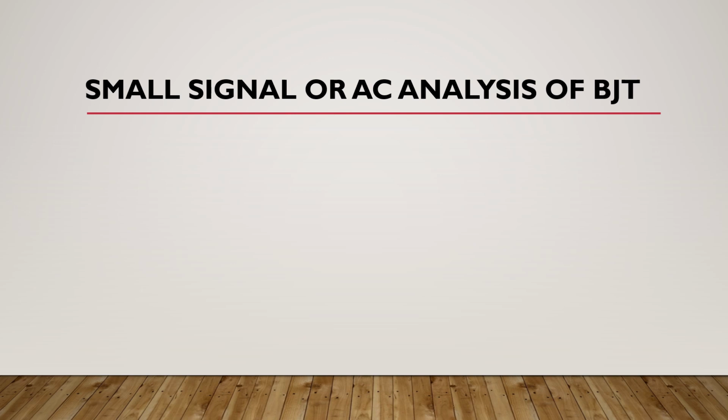Now, if you have a transistor configuration like this, and the arrow is here, it means this is an NPN transistor configuration where we have RC here, here we have VCC supply voltage, and as you can see this source is connecting base and emitter, and it is a DC source as well, so we can write it like this, because we know that DC quantities are written in uppercase with uppercase subscript.